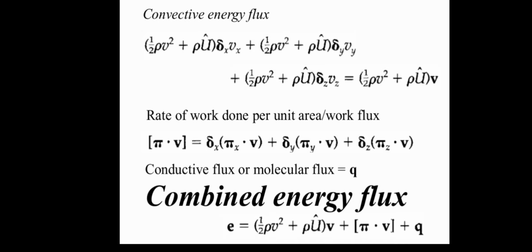The concept of energy flux is fundamental where we perform an energy balance on a control volume or a shell within a flowing fluid. The shell energy balance equation presented states that the rate of combined energy flux in minus the rate of combined energy flux out, plus the rate of work done on the system by external forces, plus the rate of energy production, equals 0. One important application is the phenomenon of viscous heating. As discussed earlier, work done by viscous stresses can lead to dissipation of mechanical energy into thermal energy, effectively acting as a heat source within the fluid.